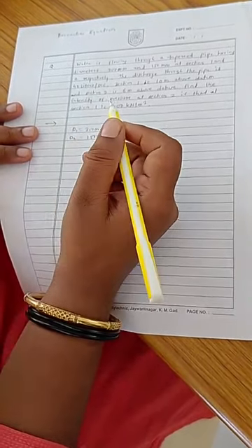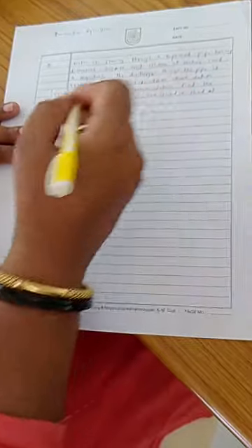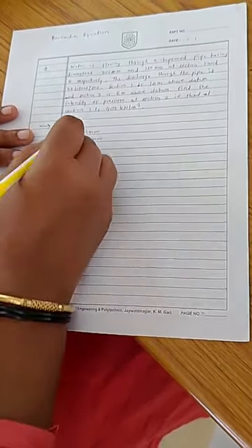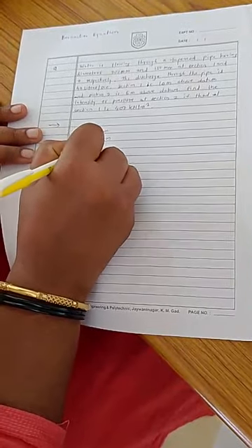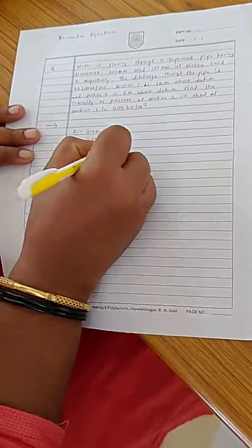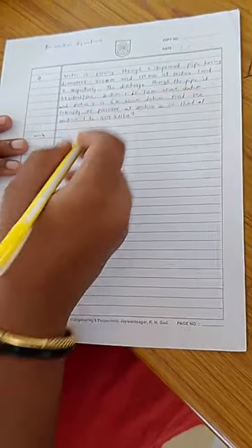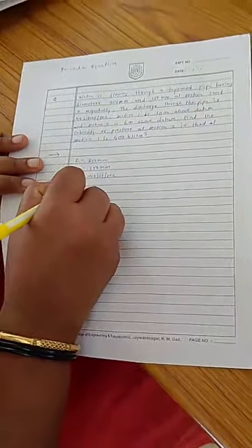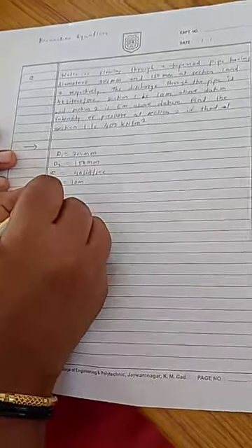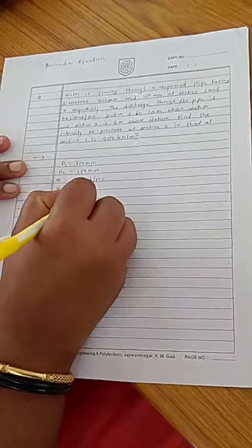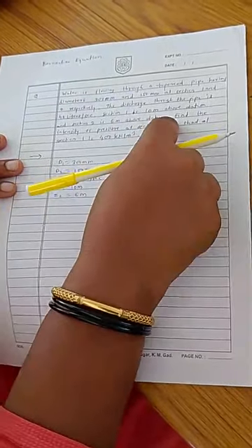At section 1 and 2 respectively, the discharge through the pipe, so Q, is given here as 40 liters per second. Section 1 is 10 meters above the datum, so Z1 value they have given as 10 meters, and section 2 is 6 meters above the datum, so that is Z2 value they have given as 6 meters.